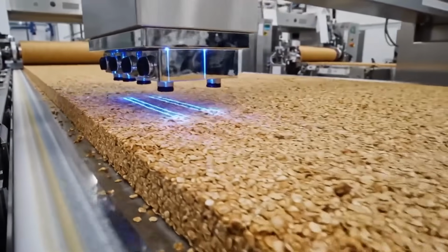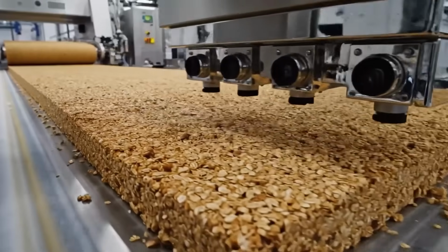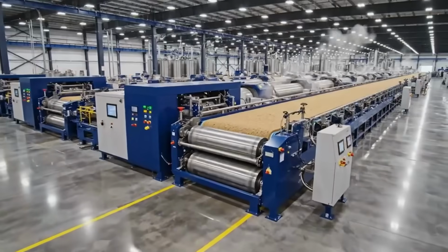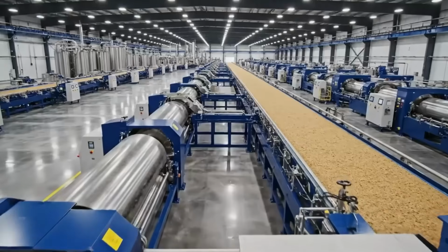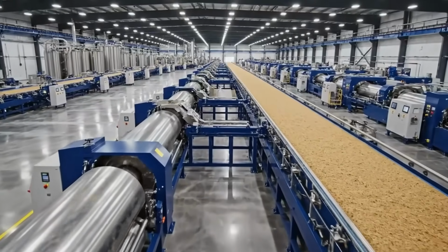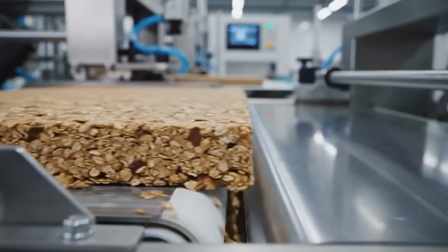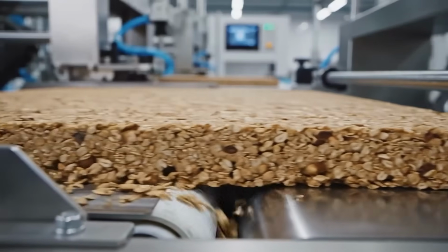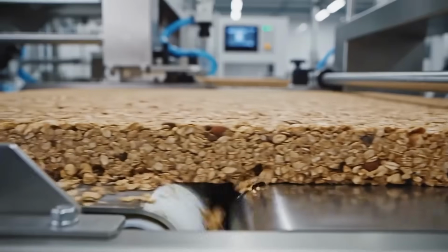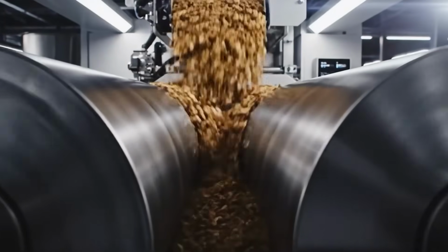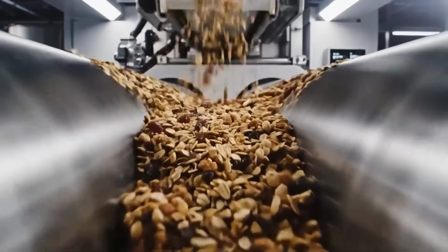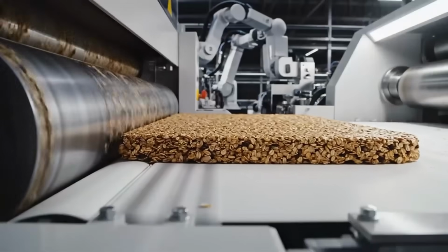After baking or cooling, the slab may be conditioned before cutting. Conditioning allows temperature and moisture to equalize across the slab thickness. This reduces internal stress and prevents edge cracking. Conditioning also stabilizes the surface so blades do not drag. For baked slabs, conditioning can include a short cooling stage to bring the slab to a consistent cut temperature.